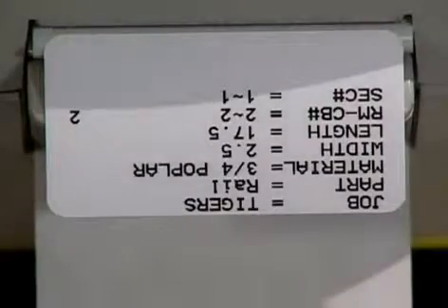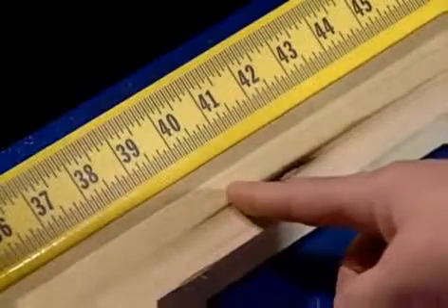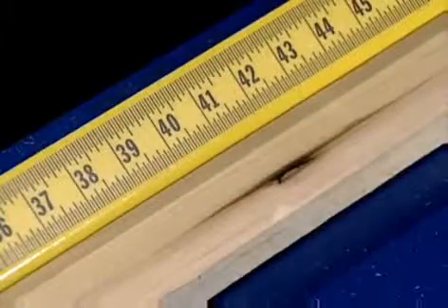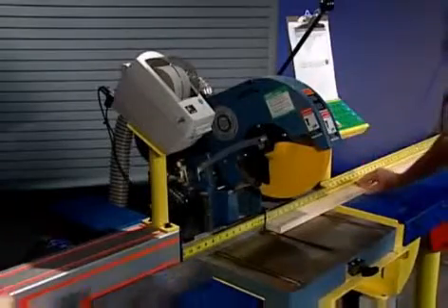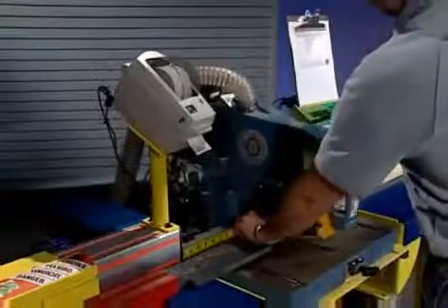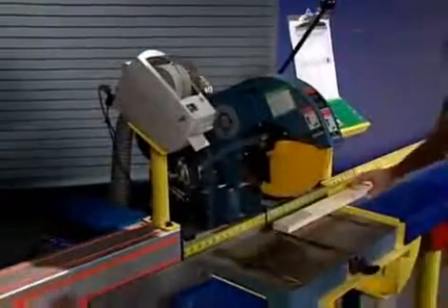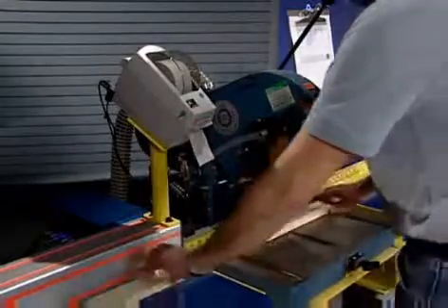After the defect is removed, Ed looks for the next defect. There is another knot at 40 inches. Again, he enters the usable stock length into the controller. The Optimizer figures out the best use and the stop moves to position. Ed has finished the cut, and it looks like the Optimizer can get more pieces out of the usable length.